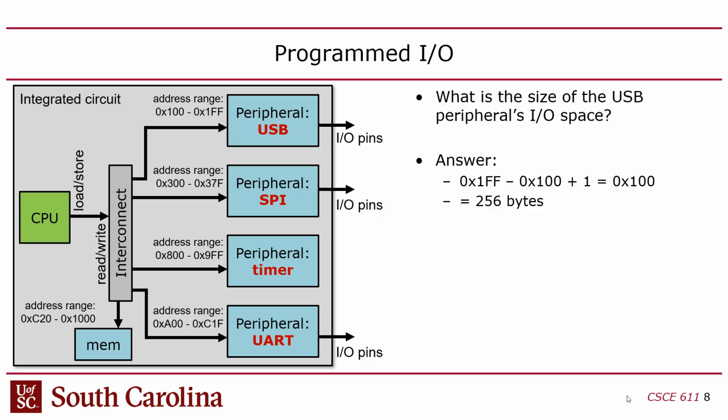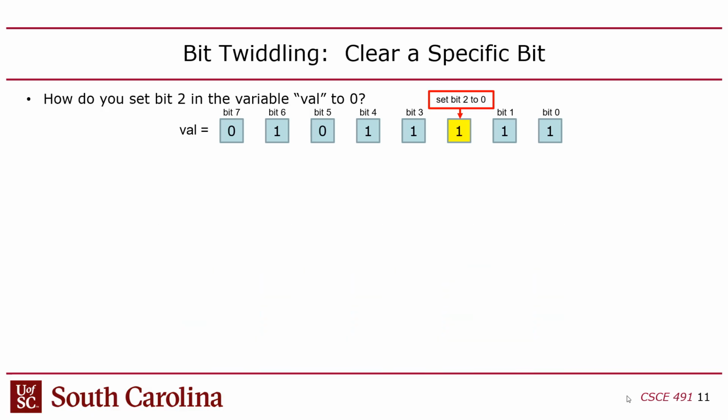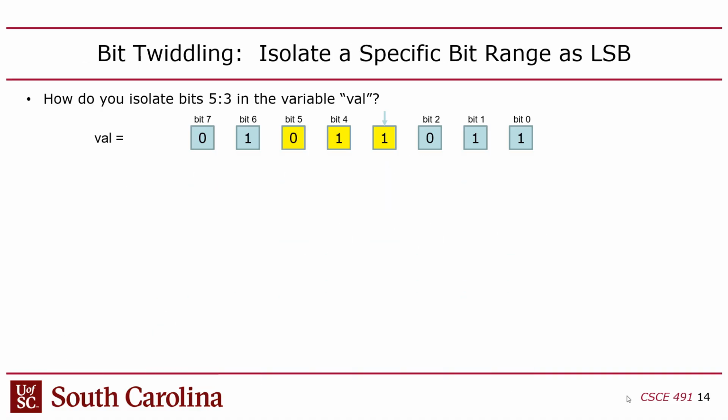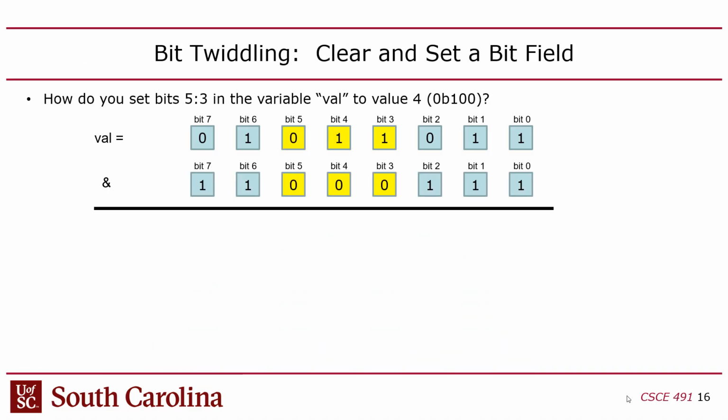Now, you could potentially reuse the same pins for address and data, but the point is that there's not enough pins on the ESP to do a parallel interface externally. But internally we can. So all this programmed I/O stuff is internal. Does that make sense? Okay, so when I say peripherals, I could be referring to an on-chip peripheral or an off-chip peripheral, like something on the circuit board that the chip is talking to.